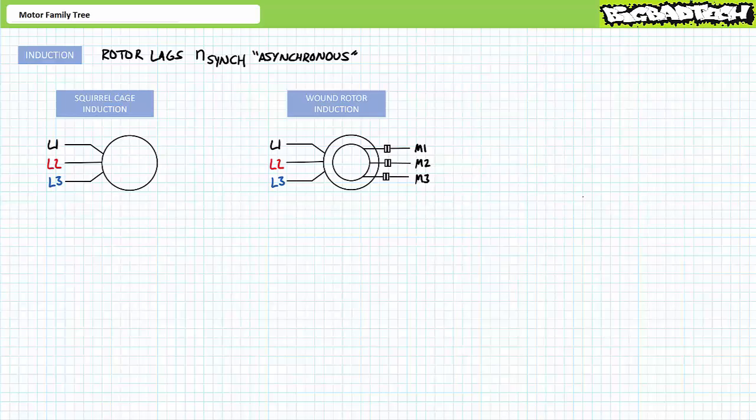Induction motors, however, establish an electromagnet on the rotor using different means. Obviously, the means of doing so is via induction. Induction is a fancy term used to describe a magnetic, not physical link between two circuits. You'll recall we examined inductors and transformers in previous lectures at the Big Bad Tech channel. There are two common types of three-phase AC induction motors: squirrel cage induction motors and wound rotor induction motors.